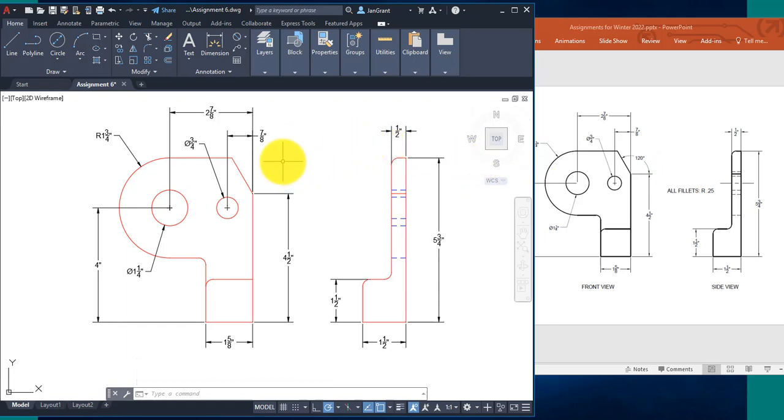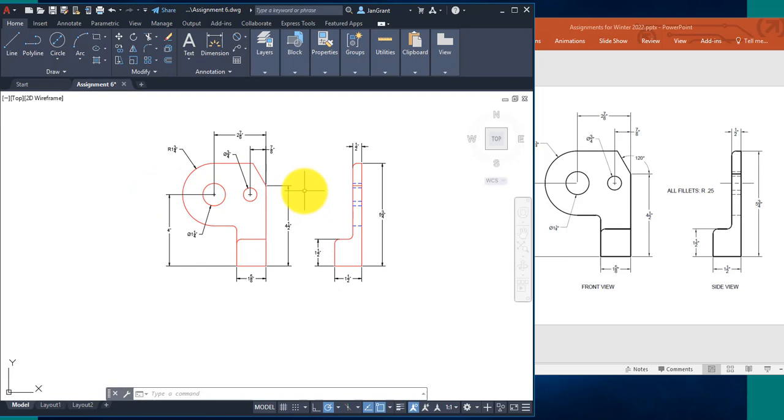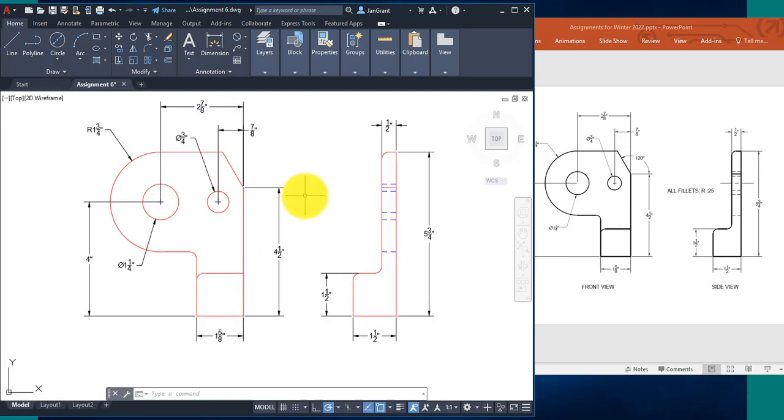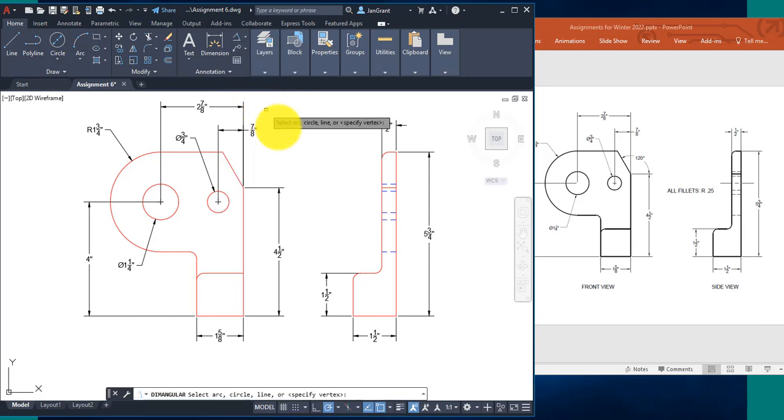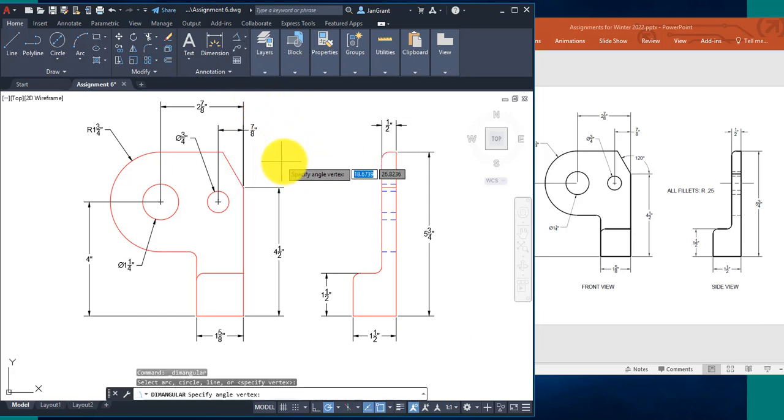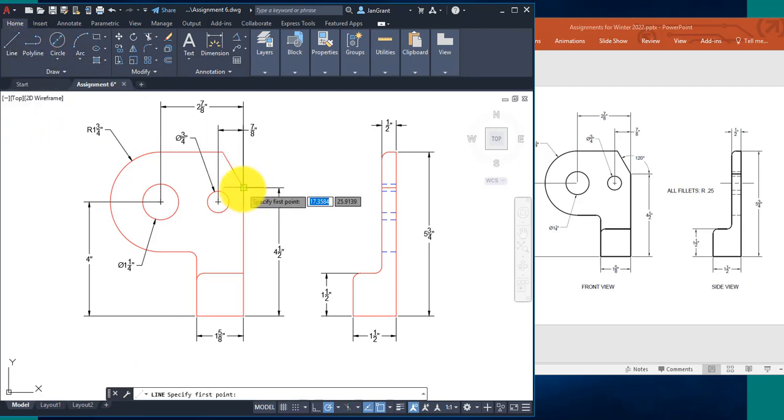So since we're still in this mode, and we're in the dim text layer and we're working on this, let's go ahead and work with this angular dimension. So right here, underneath linear, we're going to click on angular. Oh yeah, we can't place it, escape out of that until we have another line. It doesn't matter what type of line it is. Just a line from this corner going out right there. Just a second line, because it won't let us select the linear line.